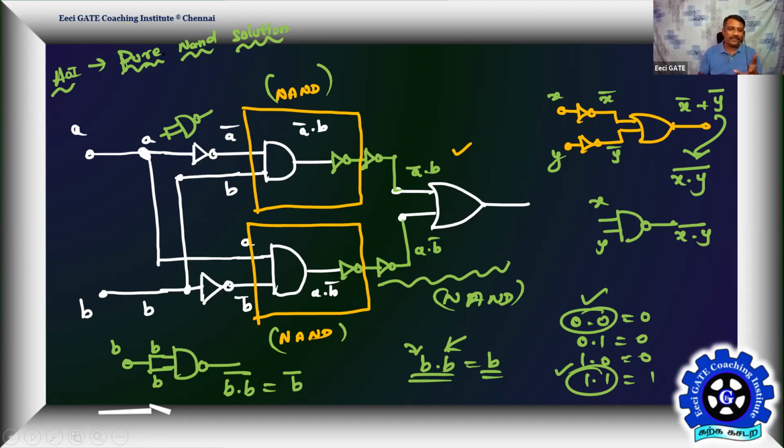Yes or no? Because how many NANDs does it demand? All of you, 5 NANDs. So one NAND IC will have 4 NANDs, and 2 NAND ICs complete your design. Because it is a pure NAND solution, even with respect to the demand of ICs, it's a minimal cost. But anyway, we'll go with the budget of CMOS.